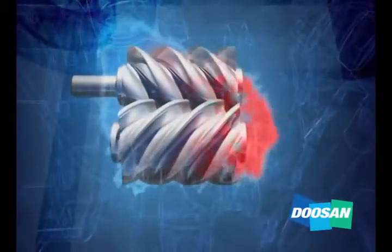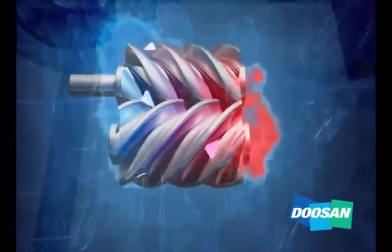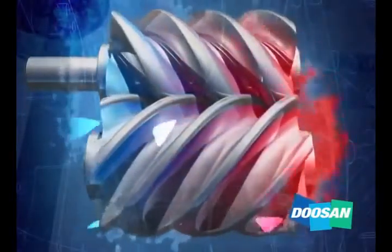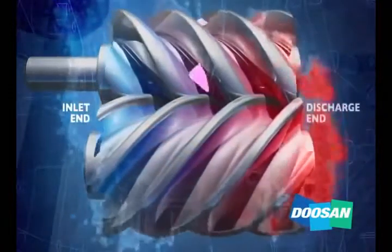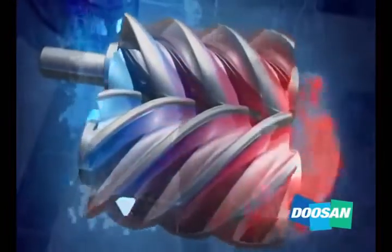The amount of air that fills the air end is measured in cubic feet or meters per minute. As air travels along the helical rotor flutes, the space storing the air gets progressively smaller. Since the air cavity between the rotors is larger at the inlet end and smaller at the discharge end, air becomes compressed, creating significant heat.